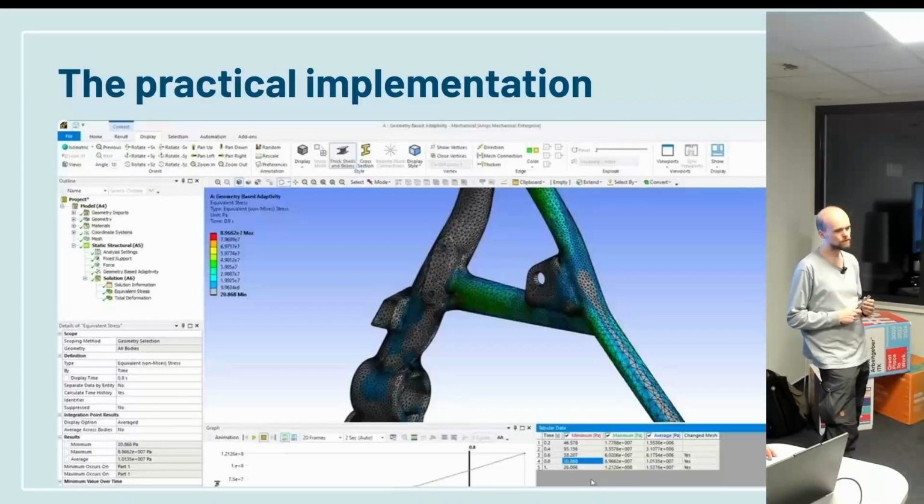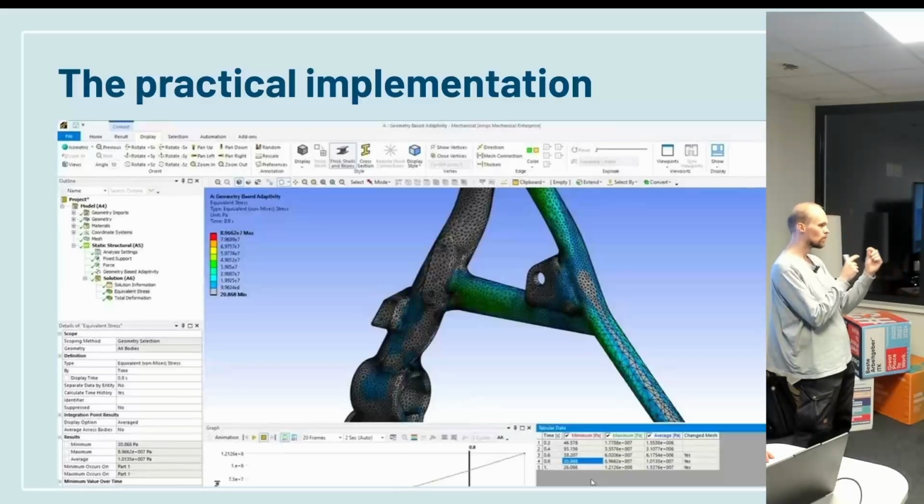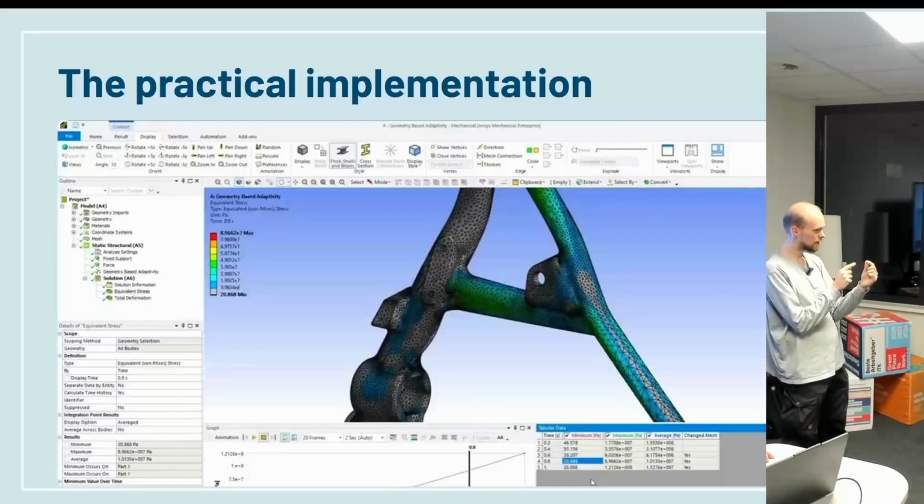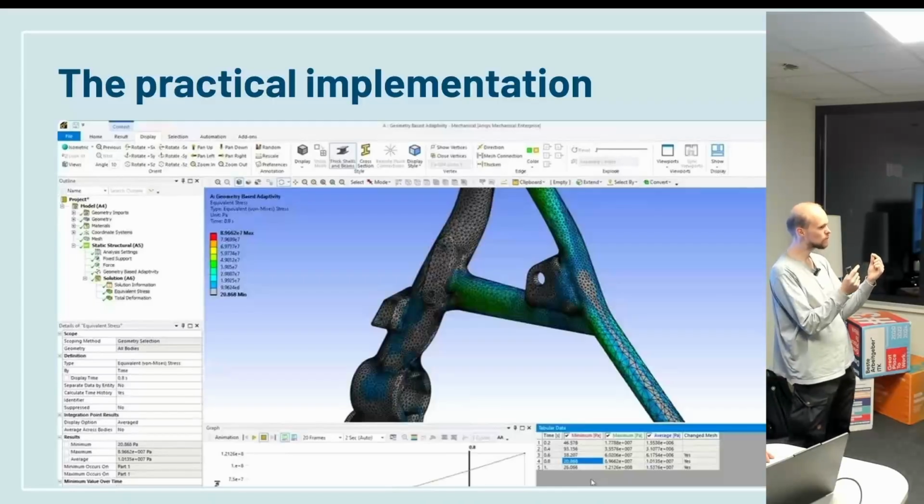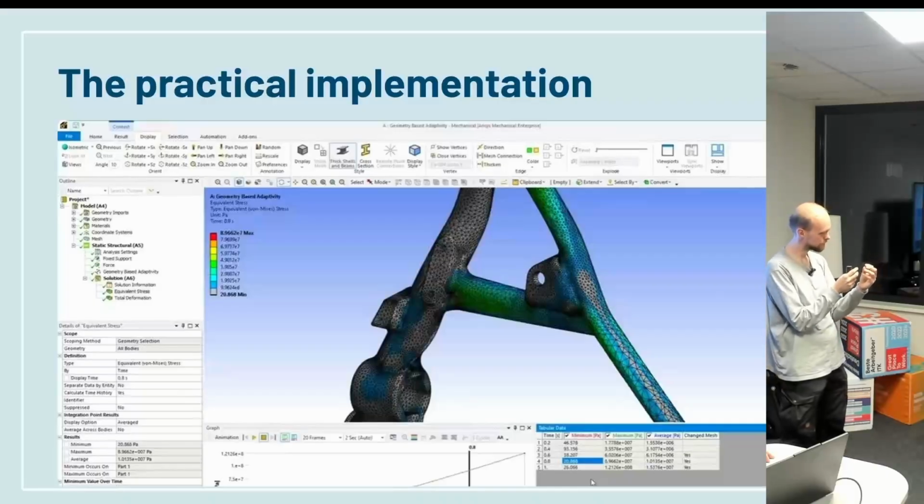You can derive finite volume theory as a special case from FEM, if you like, mathematically. You can see it like that. It's a special case of it. The problem in fluid dynamics is if you have a vortex. This vortex must be bigger than the cell it is in. Otherwise, you can't see it anymore, because then it wouldn't produce flow between cells.